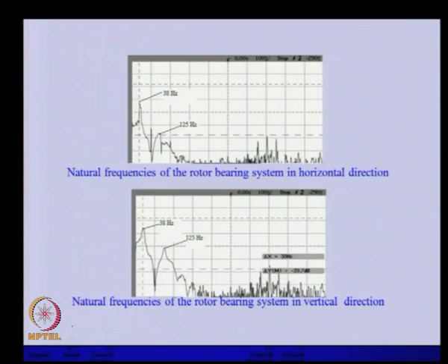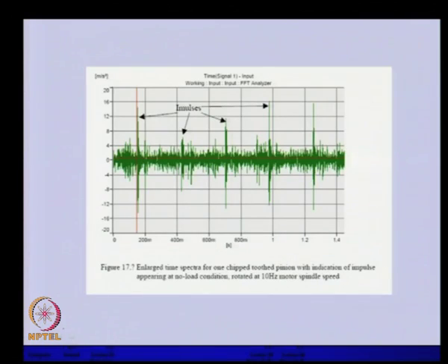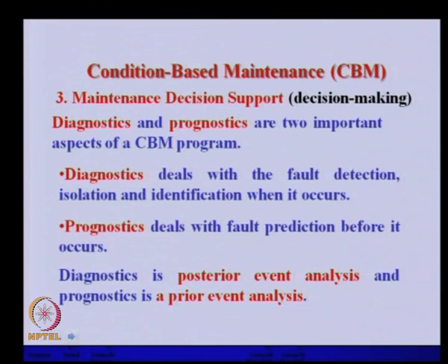So, for some data, like frequency domain data, we can perform free vibration analysis and pinpoint the natural frequency of the system. The predominant peak we can collect, and that will be our database. Or, as we have seen in the previous lecture for gear, if we have a chipped tooth of a gear, then we can have this kind of impulses. So, that information can be collected. These are some of the data types, but we can have more of such types.